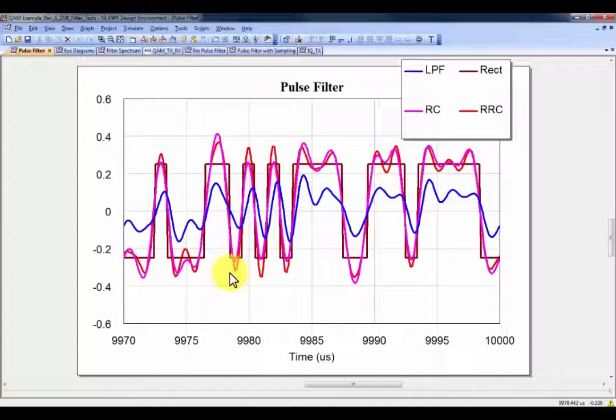However, to be honest with you, I really couldn't say that the pink or the red or the blue is better than the other. I can sort of see that pink and red look a little bit better based upon our target sinc function, but the blue seems to have peaks in the same areas. So what we want to do is figure out a way where we can better compare these, and the way to do that is basically to think about a receiver. How would we receive these pulses, and what would they look like?